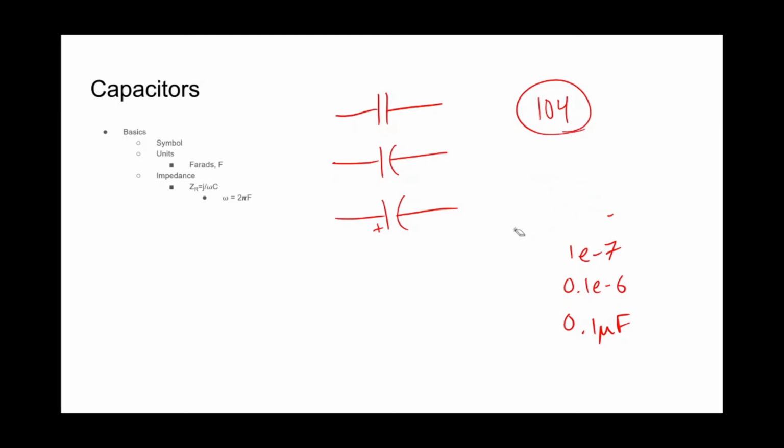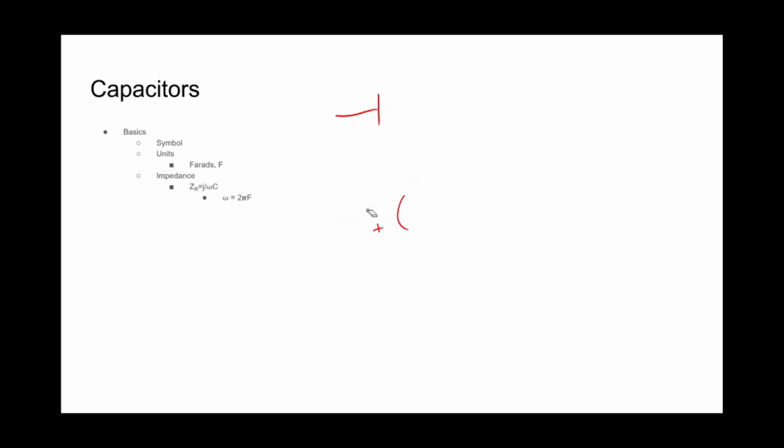All right, let's talk about impedance. So impedance, like I like to put it, is the resistance towards frequency. Remember, for a resistor, Z sub R was just R. Now in this case, we're looking at capacitors, not resistors. So Z sub C, like it says here, is 1 over j omega C. And what this gives us is omega, or the radians of our frequency. So to convert to hertz, you just divide by 2 pi, or for frequency you would multiply by 2 pi to get omega.